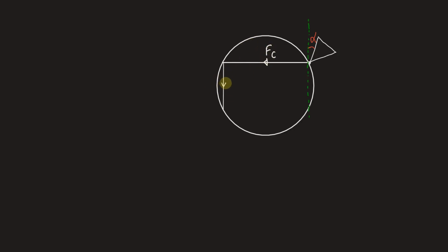So let's say this is the tool, rake angle is nothing but the angle at which this tool is being placed with respect to this vertical line, which is alpha. Now let's draw the force diagrams. Whatever is the orientation of tool, cutting force will always be in this direction, Fc. Then for orthogonal turning we have this force Ft perpendicular to Fc.